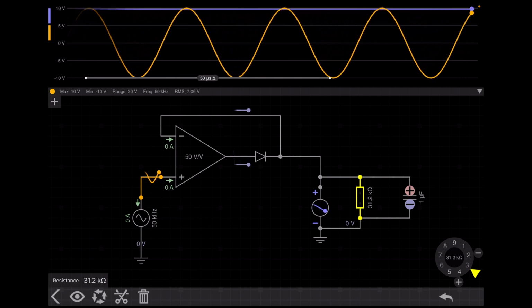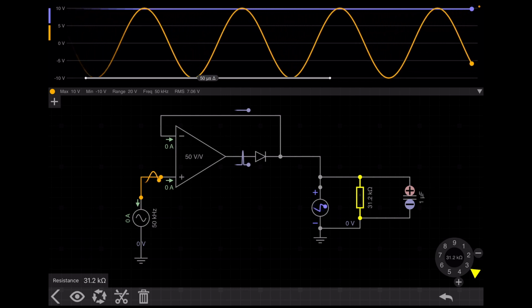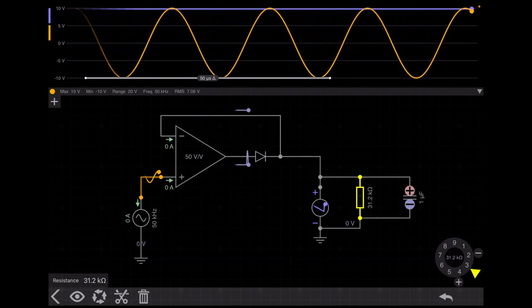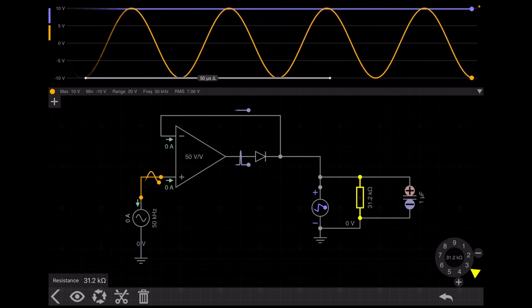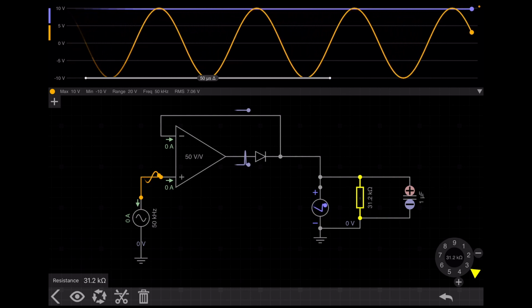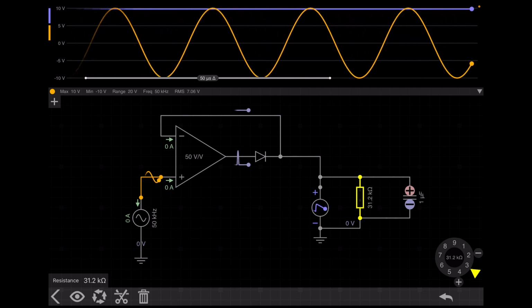In the paper, just do the calculation and state that this is a half wave rectifier. I connect a capacitive filter, and as this is a capacitive filter without any resistance, there will be no discharge, as the time constant will be infinite. So it is just a peak detector circuit.